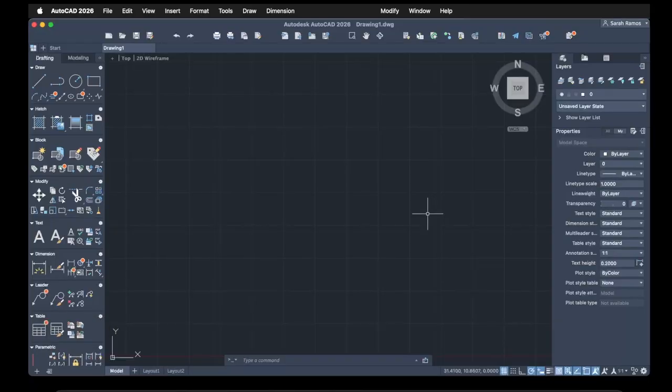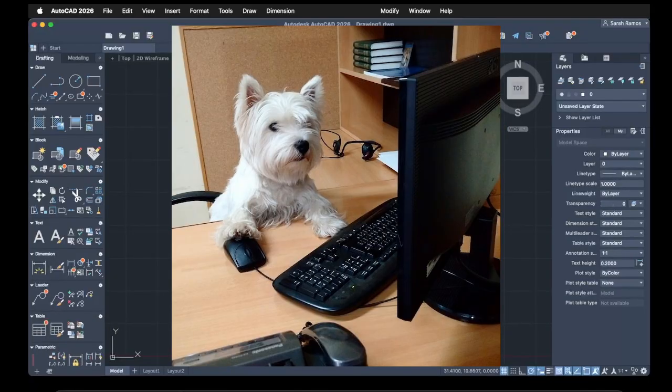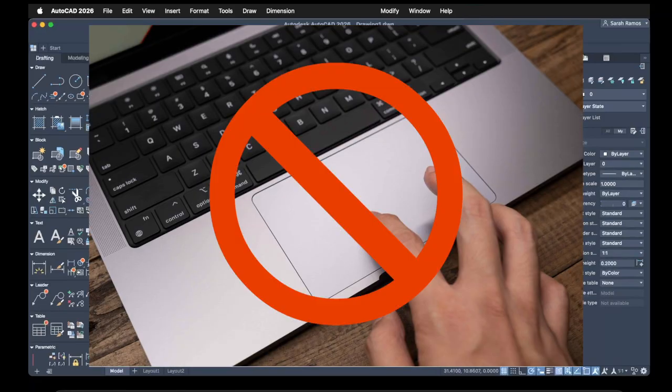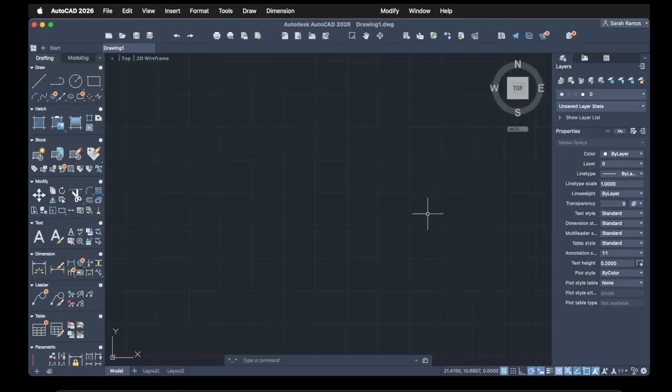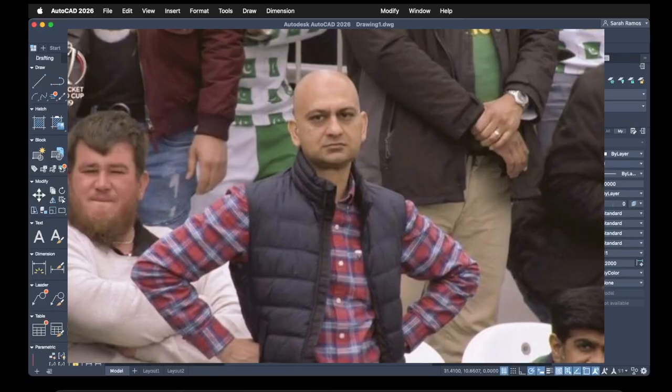First thing I want to say, your left hand is your keyboard hand, and your right hand is your mouse hand. You should be drafting with a keyboard and a mouse setup because doing it on a trackpad is incredibly inefficient and weird to zoom in and out with. Is it possible to do on a trackpad? Sure. Some of you won't listen to me and will do this on a trackpad anyway. I can't stop you from being wrong, but I can make this face at you.